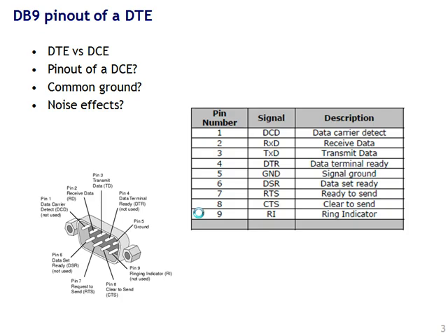Typically what you find is there are a few different hardware control pins which may or may not be used depending upon your application. If you're hooking this to a modem, it's really good to know if the modem has got a carrier. So if you can hear the carrier, that's like the high-pitched whistling sound you might get from a fax machine, you get DCD, the data carrier detect.